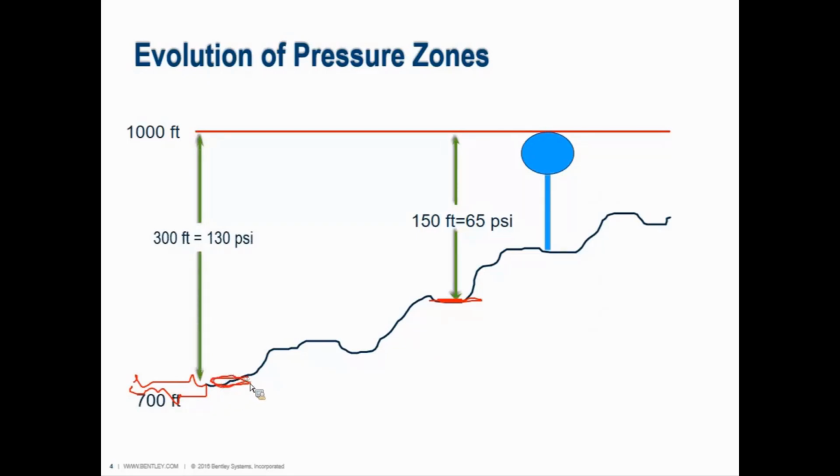Okay, you look at another location, and you think, well, what if we built a subdivision down here by the river? It's an even better view. In fact, you can even cast your line right into the water off the back of your house. Boy, wouldn't that be great? However, because of the static pressure, you've gone further down the hill, and now pressure is 130 psi.